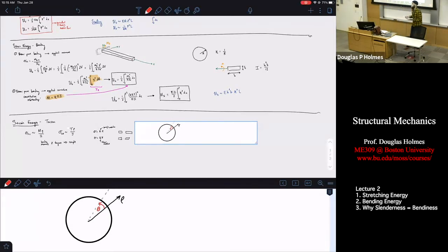We change coordinates because circular rods are easier to analyze with polar coordinates than Cartesian coordinates, but they're measuring the same thing, which is how far are you relative to the center of your object. And the center of your object is important because when you apply pure bending or pure torsion to an object, there's no stress here. Oops. There's no stress here. The stress varies linearly from my red dot here out to the edge of my beam.